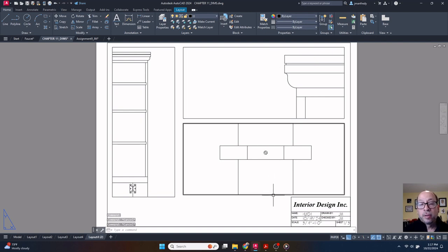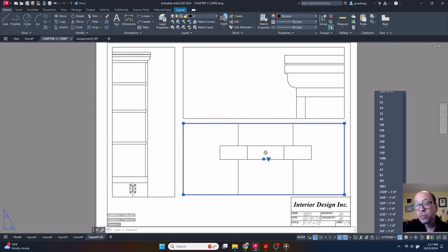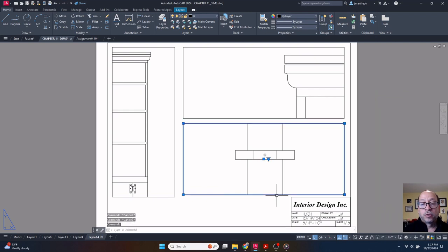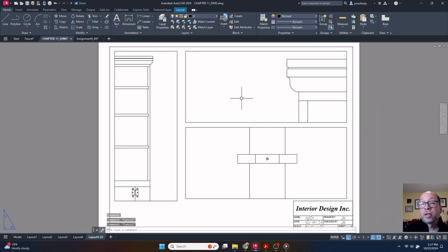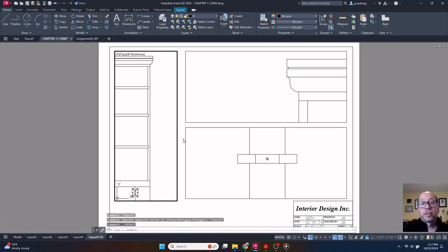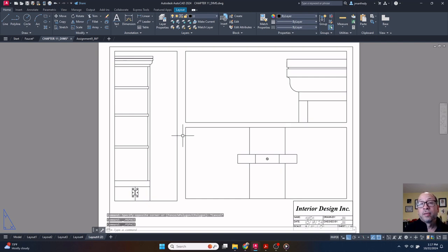And this one here, this drawing should also be 6 inches equals a foot. It shrunk a little bit, and I'm going to lock it as well. Only after all that work has been accomplished do you then do dimensions. And when you do dimensions, you do them inside these M views to make sure that the scale shows up appropriately for the information that you are measuring.